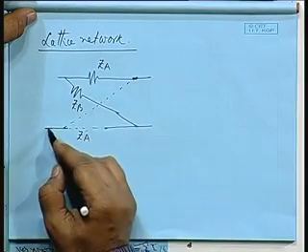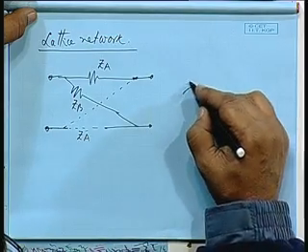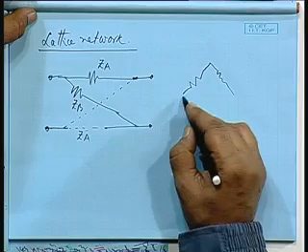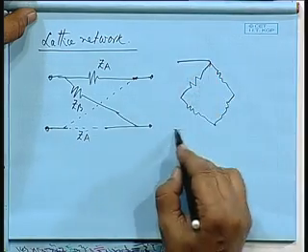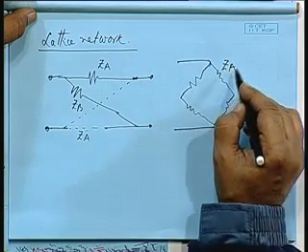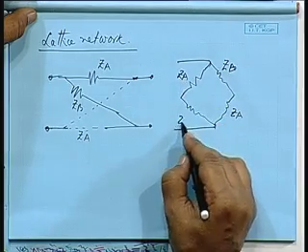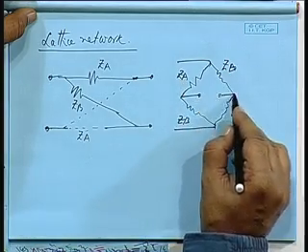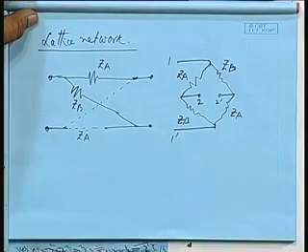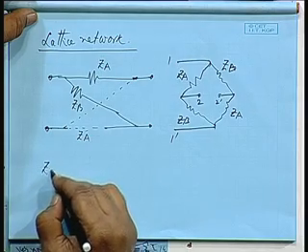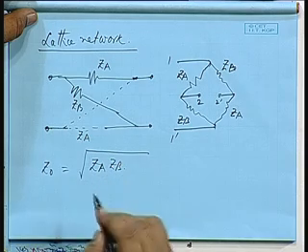This is Z B and this is Z A. This can also be seen as a bridge network like this. This was say Z B, Z A, Z A, Z B, and these are the output terminals 2, 2 dashed, 1, 1 dashed. And for this kind of a symmetric network, we saw Z naught, the characteristic impedance, was the product of Z A and Z B, under root.